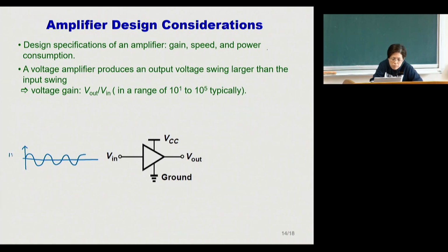So this is probably 1 millivolt. It's very small, and it's very hard for me to do ADC conversion because the signal itself is too low. So I want to make an amplification first, a pre-amplification, pre-treatment of the circuit. Then this voice will be amplified, and what I expect is that it will look something like this.